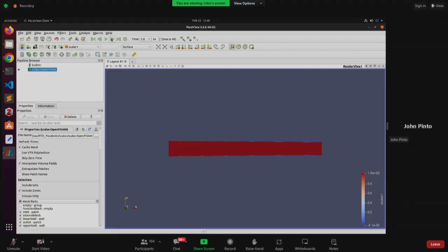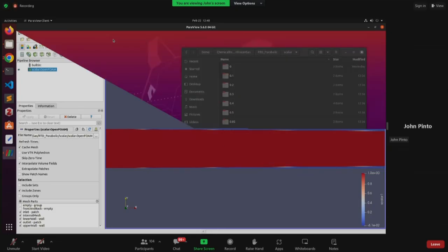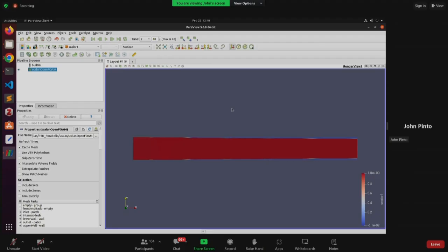But if you see, because we have given a no slip boundary condition at the walls, we have a region where the scalar has not yet diffused. Because the flow over there is very slow, right? In the boundary layer, the scalar is not penetrating that, so it will take a long time for the flow to reach over there. But that is not what we are seeing over here. So the scalar will develop this way when the walls are stationary. In this case, the walls are stationary and the velocity profile imposed is a parabolic profile.